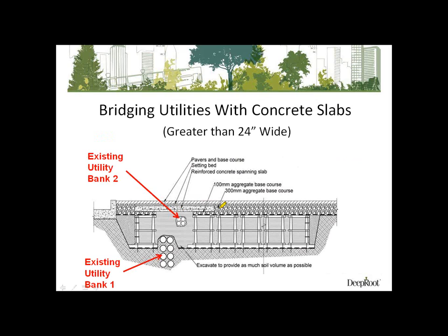Now, we started to move into some projects where we are spanning larger gaps. These involve designing more custom designed, either precast or cast in place, concrete slabs. We've done them at various different dimensions, but the concept is that you have a reinforced concrete slab that is supported on one side by a pier of Silva Cells and then on the other side by a pier of Silva Cells.